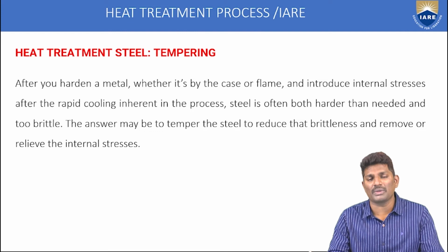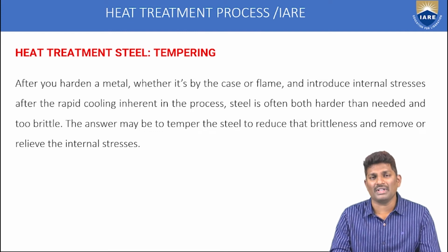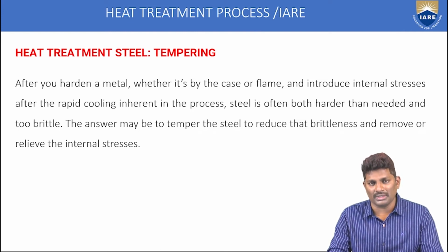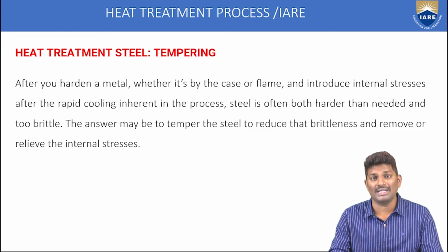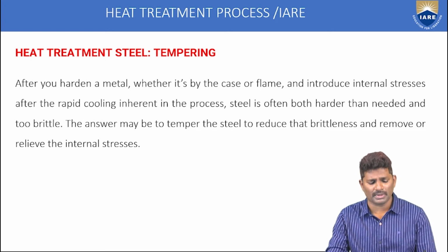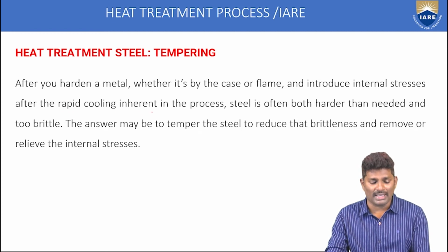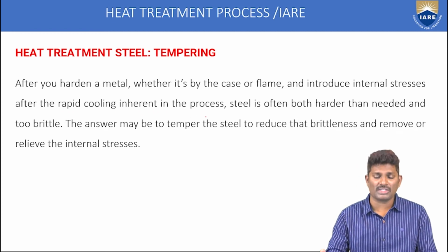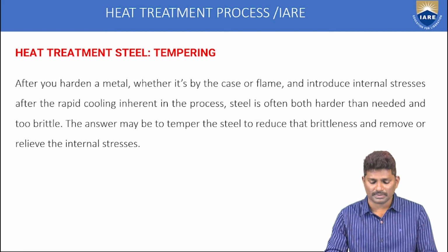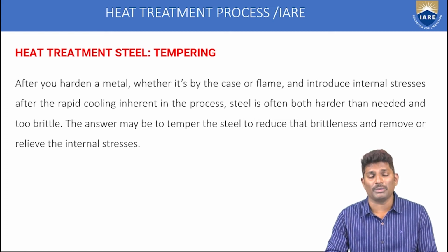So during this rapid cooling, what is happening? There are a lot of internal stresses developed inside the body. So in order to remove those internal stresses, we are trying to do the tempering process. So during the rapid cooling, steel is often both hard and too brittle.